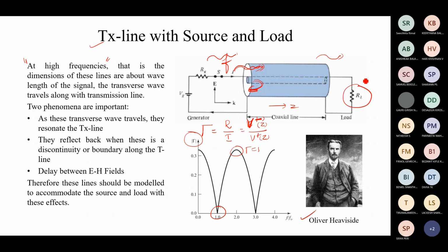And this is completely resistor. There is no RLC. The source is also a resistor. Therefore, this behavior must happen because of this transmission line, which is not simply a resistor. There must be some plus reactance term. In fact, the reactance term itself was introduced by Oliver Heaviside.